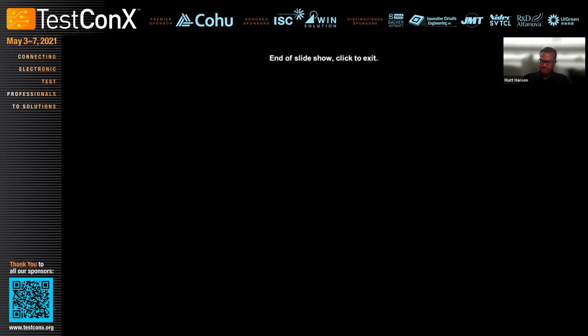Okay. What about the lifetimes? What is the typical lifetime for contacts during high temperature testing, and what's the effect of contamination, especially for high temperature testing? High temperature testing is a very hard question to answer even for a normal socket. It depends on so many variables, right? But elastomer is just mechanical touchdowns. We're getting hundreds of thousands depending on the application.